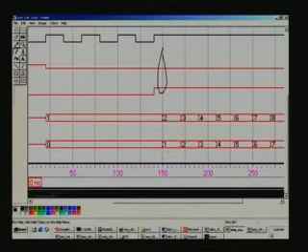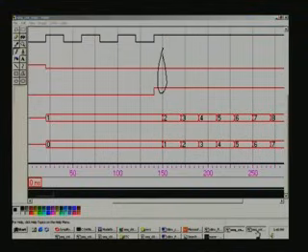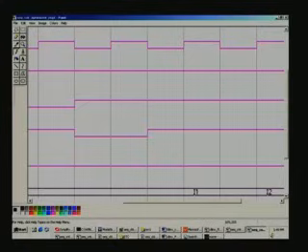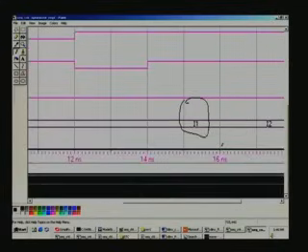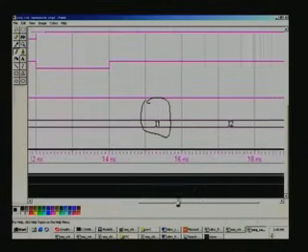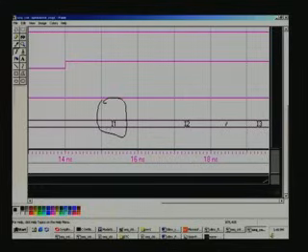You can see it is exactly aligned, so any count change is exactly aligned with the positive edge of the clock here, whereas in the post-synthesis netlist there is a delay here, that is what we have seen here. Is it clear? And the counting as usual progresses in this fashion.